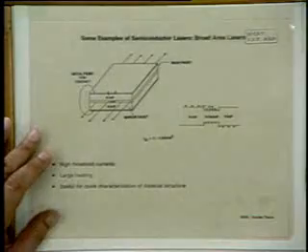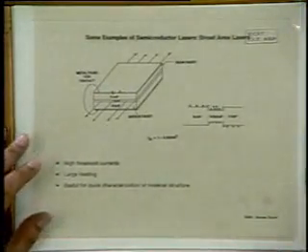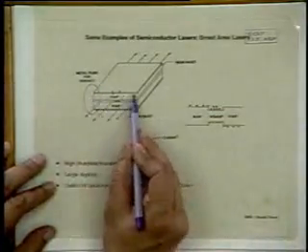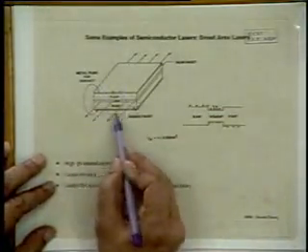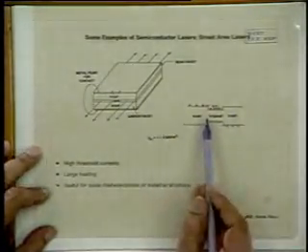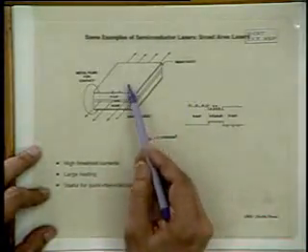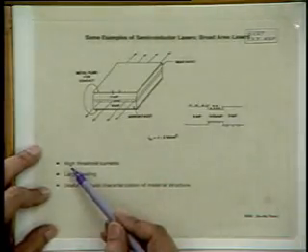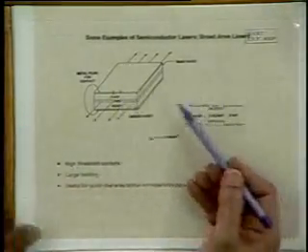Now, if we come to, okay, I think I have a few graphs here. I don't know if I showed this. Okay, this, if you can see, this is a broad area laser. So you have an overall area contacts back and front. Okay, so this is double heterojunction indium gallium arsenide phosphide. You have high threshold currents, large heating. Okay, but it can be used for quick pulsed characterization, whether the light is coming out, whether it's lasing or not.